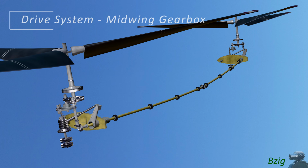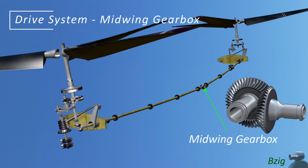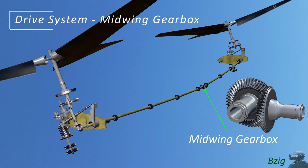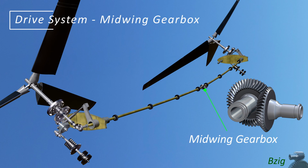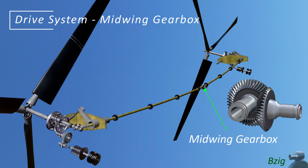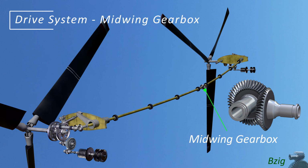The midwing gearbox is used to extract power from the drive system for hydraulic and electrical service. Earlier I had said that tilt rotors are capable of all-engine-out autorotation, but they're still fly-by-wire with hydraulically boosted flight controls. And like many large aircraft, they would be uncontrollable without hydraulic and electric service. This is why it's necessary to extract power from the drive system to power the flight controls.